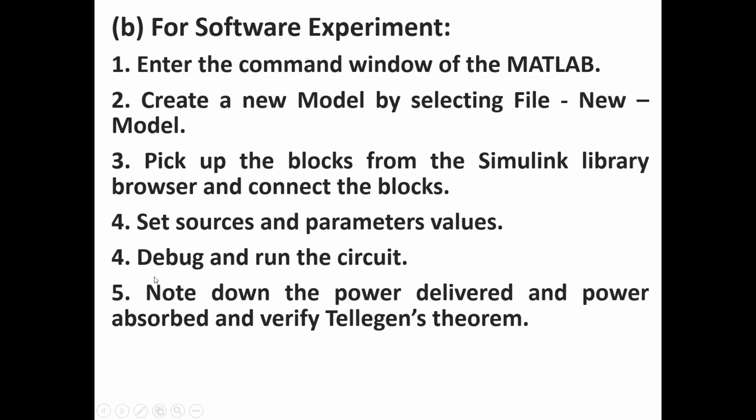After that, you have to debug and run the circuit. When you debug and run the circuit, you must observe that power delivered is equal to the power absorbed. Then only Tellegen's theorem will be verified. If that condition is satisfied, then Tellegen's theorem is verified. Otherwise, it is not verified for the given circuits which are connected together and which are of same topology. Two networks of same topology.